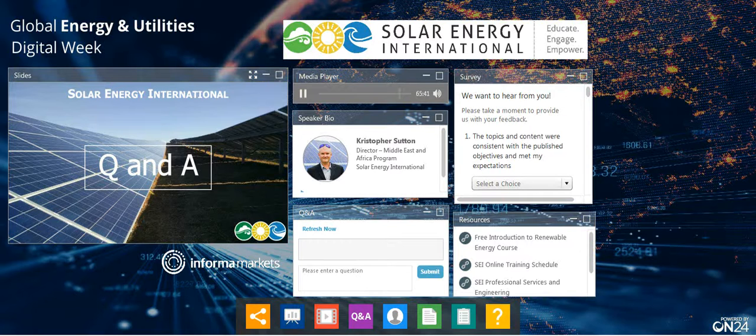So if you set this up properly, you should never damage a generator, because the control system is there to monitor, measure and adapt to the situation by throttling the solar down. How the inverter backs off the solar is a much further discussion, but a grid-tied inverter has the ability to process less energy if it's told to do so. So it's able to just reduce the output.